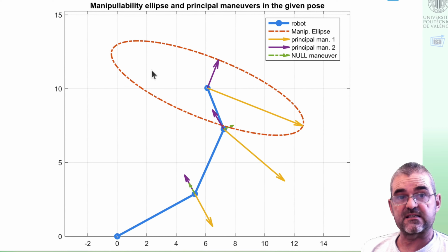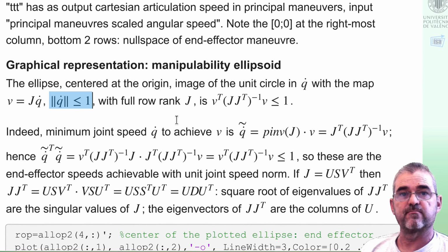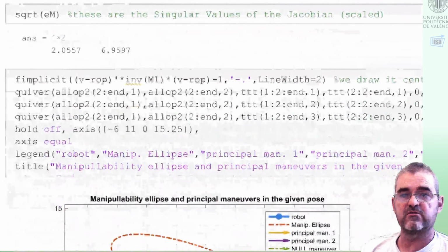We'll finish the video with a last observation saying that, okay, the underlying assumption of this ellipsoid stuff is that the scaled velocity was in the unit sphere. But come on, when I speak about saturation of physical motors, it's more likely that the extreme velocities lie not in the unit sphere but in the unit cube or hypercube in which vertices are combinations of +1 and -1. So, what is the conservatism of the ellipse approach versus this polyhedral approach?